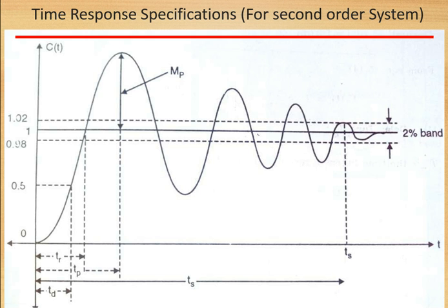Okay, so if you see here in this case, from 0 to TS, this response is called the settling time, because up to TS the system was giving you some oscillations, undershoots and overshoots, and some instability. After that the system tries to acquire its final value, which is nearly equal to 1, but practically we will not get exactly 1, so it will remain in a 2% band, or 2 to 5% band. But by standard, just consider that as a 2% band.